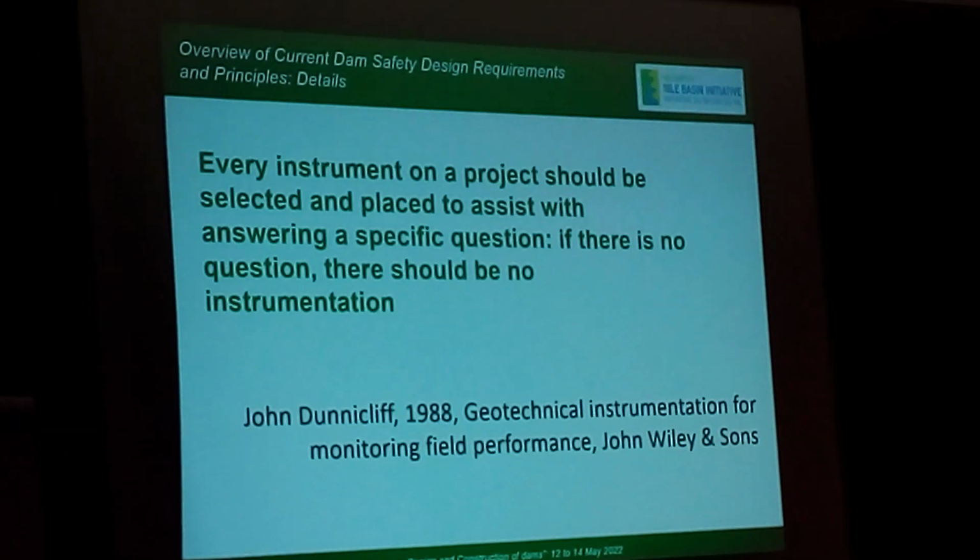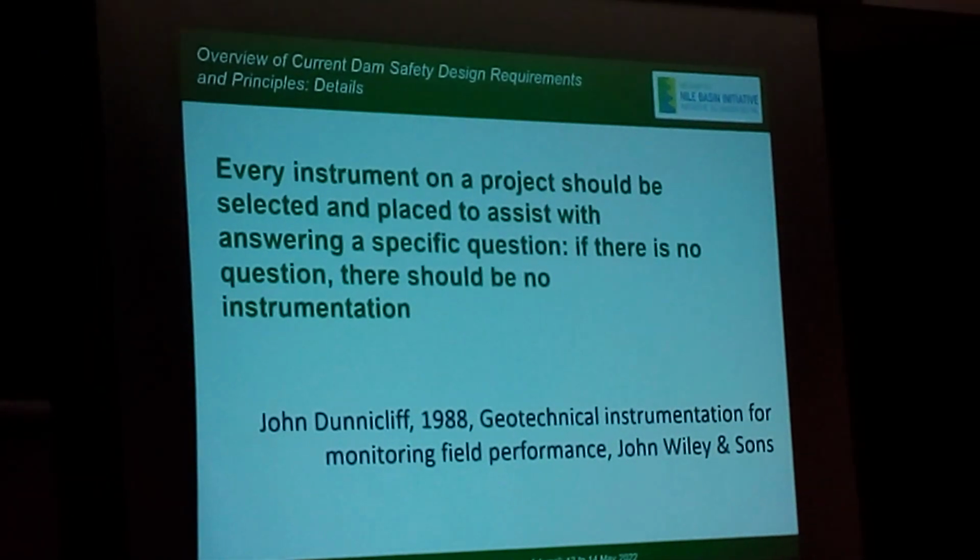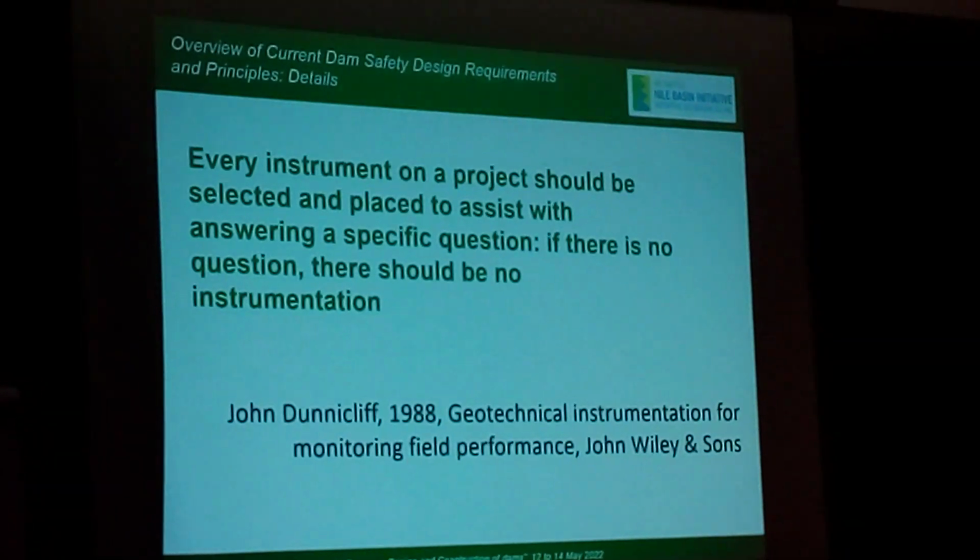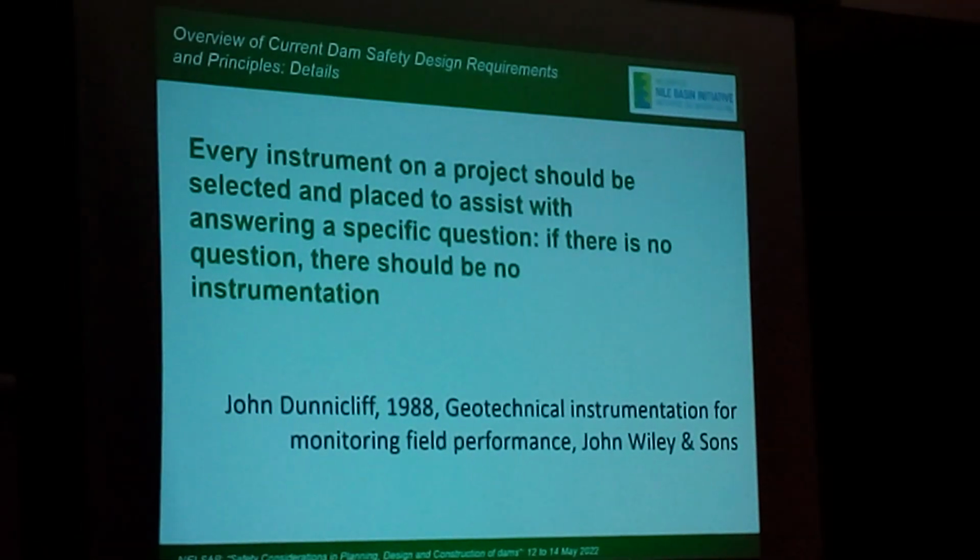But remember, every instrument in a project should be selected and placed to assist with answering a specific question. If there's no question, there should be no instrumentation. So don't copy and paste what you see being done at another dam. You have to think why.